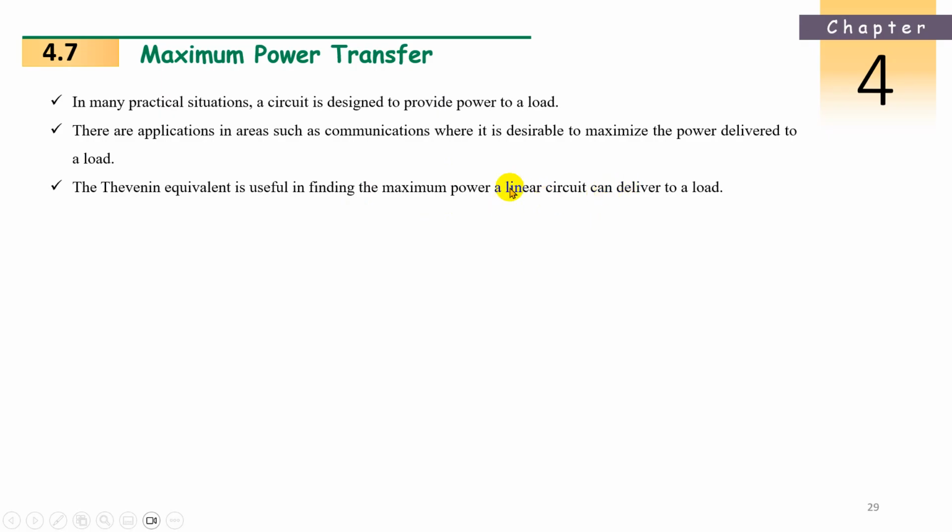It is easy because in Thevenin's, the voltage source will be in series with the Thevenin's resistance and the load also in series. So all are in one loop only. In Norton's, there will be two loops: the source current with the Norton's resistance, and the load resistance. So the calculation will be quite bigger than Thevenin's. So let's go with Thevenin's.